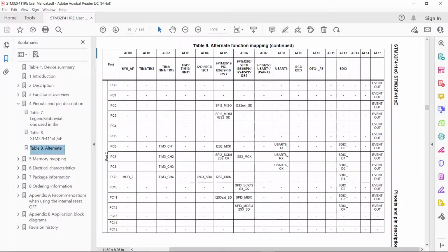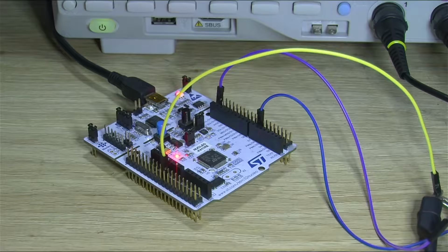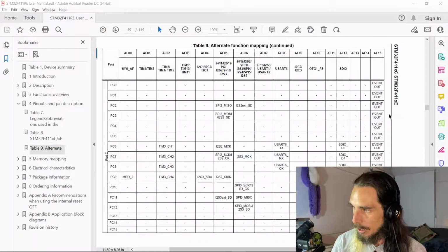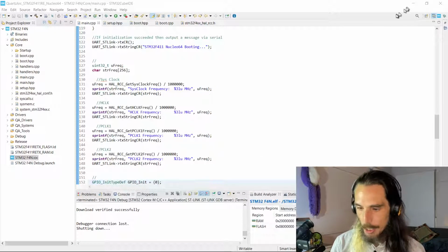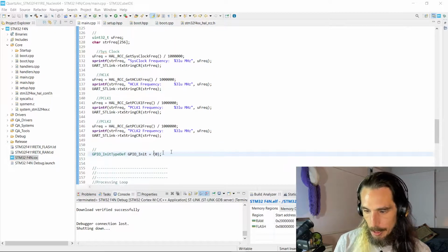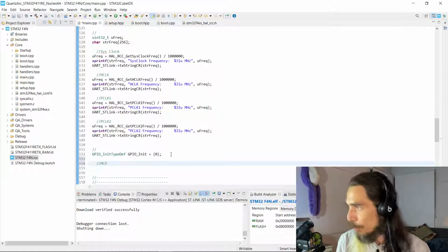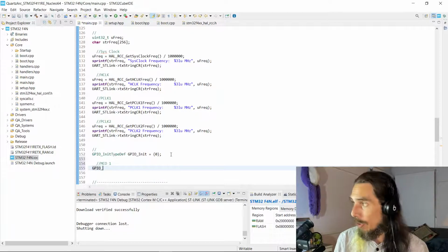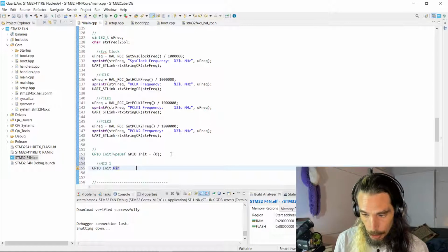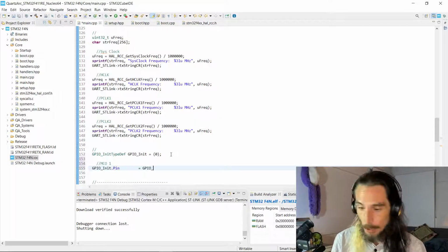We do already have those connected up in this case to the oscilloscope so that we can have a look at those, but just so that it makes it a little bit easier for you to find those specific pins if you need to, that's the easiest way to be able to do that. So let's get our first one set up. We'll use both of them because we're actually going to do a comparison between our high-speed internal clock and high-speed external clock, just so that we can see what those are actually looking like.